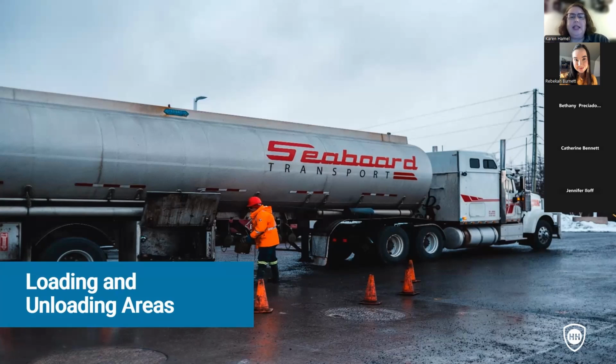And similar to this, akin to this, where are our fluid transfer areas? Where are we transferring maybe from a tote or a drum or a carboy or a jerry can into a smaller container or into a process? Where are those liquids moving? So anytime that we see those liquids in motion, that is a big potential for a leak and spill. So when the fluids are being transferred either in bulk or maybe even in a small amount, where are those leaks and drips happening? Do we have systems in place so that those leaks and drips are caught?